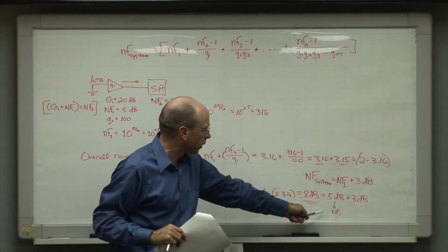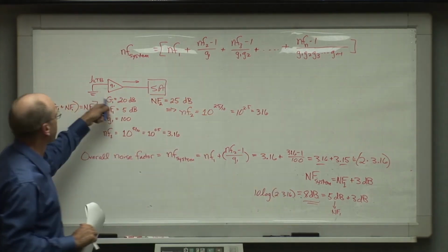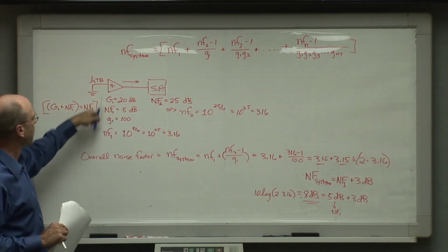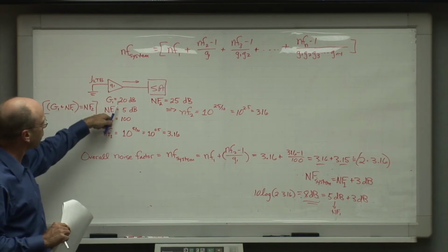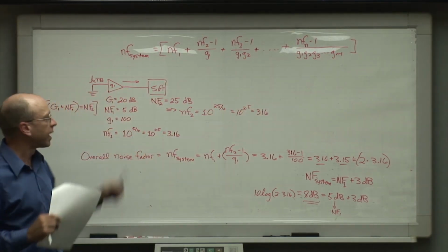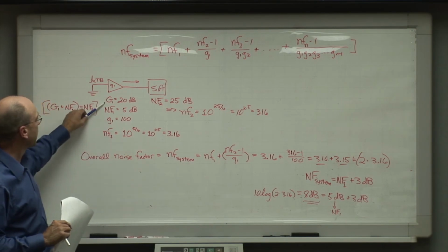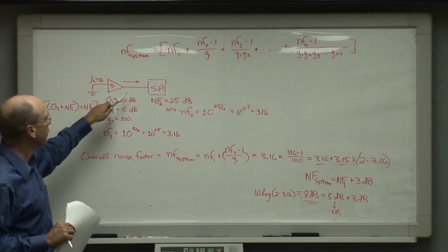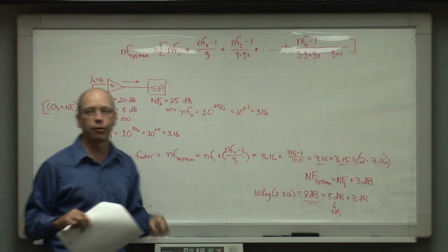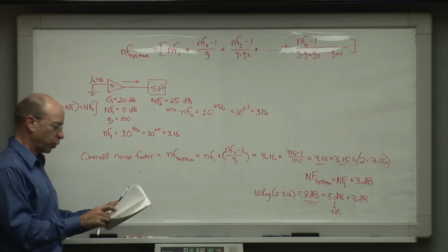That is where typically a person who's designing a radio receiver or a measurement system wants to be with a cascaded series of components. They would like the gain in decibels plus the noise figure in decibels of a given component to be just about equal to the noise figure of the next component in the cascade after that, and so on down the line. If you can design it that way, and we'll see in a minute, you will be able to get most of the benefit of that gain in terms of seeing an amplified signal, and yet you won't eat up, and we haven't talked about this yet, much of the dynamic range of the next component in the series. And so you'll see this with well-designed radios over and over again. And I'll also tell you where people can go wrong with that.